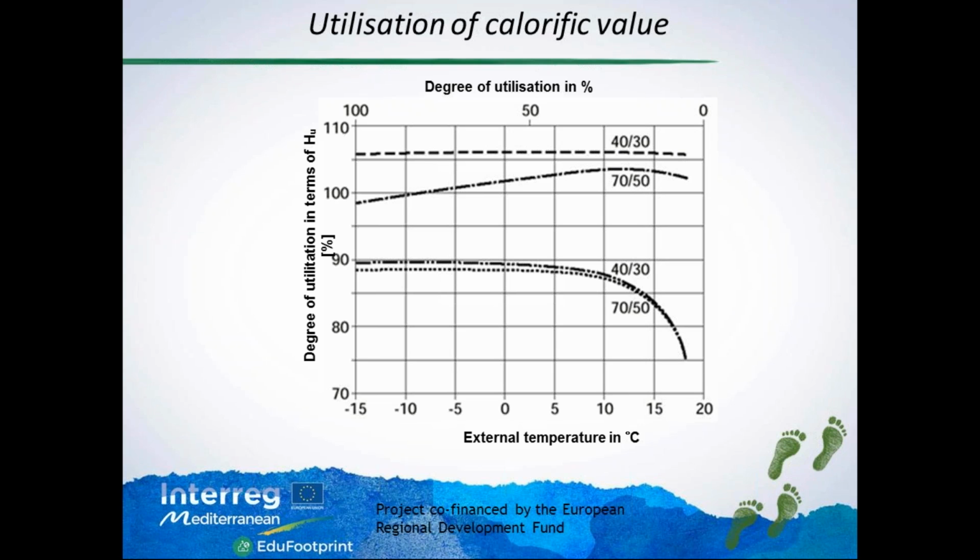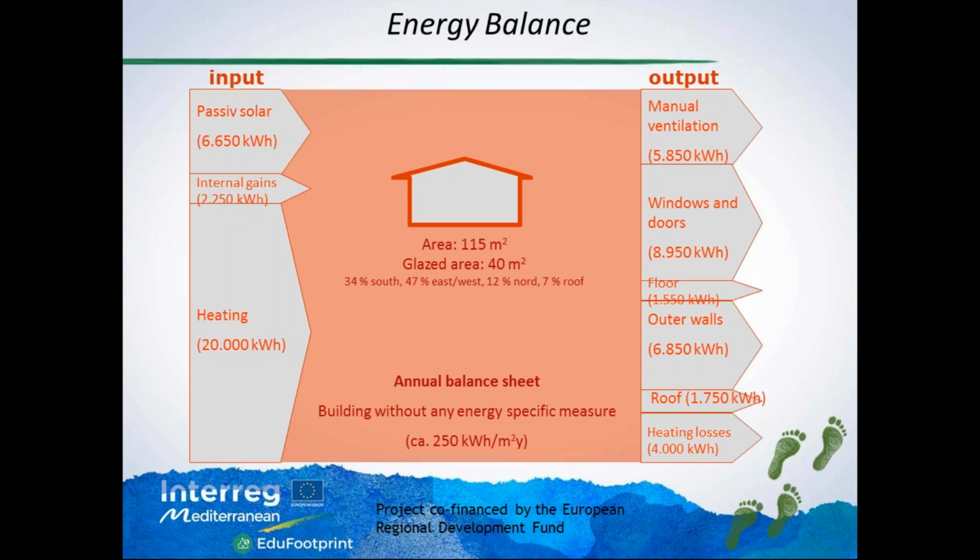This is the reason why condensing boilers often are not used very well, and people are expecting a very good saving from substituting a heater with a condensing heater, and at the end of the year they see there is no real saving, because the temperatures were too high, and in the condensing boiler there was no condensing process. No condensing process, the 11% more that we could use cannot be touched. So it's just like a normal boiler.